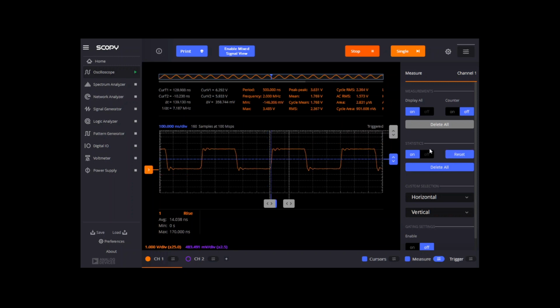If I zoom back out and reset. So it looks to me like the measurement is affected by the zooming in Scopey. So does it get more accurate if I zoom in? Who knows? I think the bottom line is that this 14 nanosecond range is near the limit of what you could reliably measure with Scopey, and that's consistent with the theory from the M2K's bandwidth.